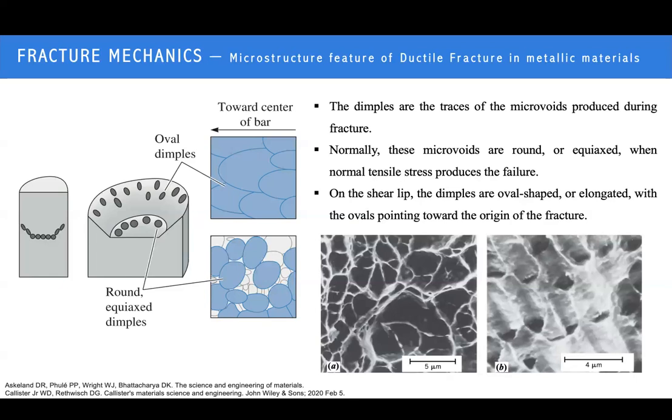By that, we can see this kind of material has good ductility, and the mechanism of the fracture is forming the microvoids at the beginning, and then these grow and coalesce until the fracture occurs through the slip direction of the fracture mechanics.